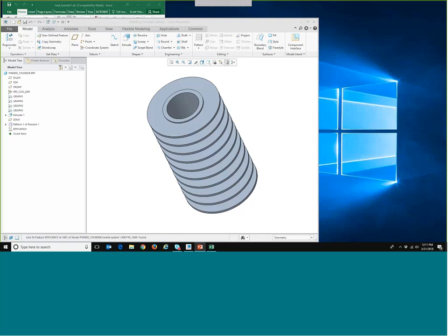Within this model, we have several graphs that are set up, and these graphs are just based off of standard efficiency graphs, and they relate to the geometry of the model. So basically what will happen is Creo Parametric will, based off of the Excel spreadsheet, we'll look at that in a second, find a value, it will then go to these graphs, and it will select the appropriate efficiency off of that graph based on our calculations.